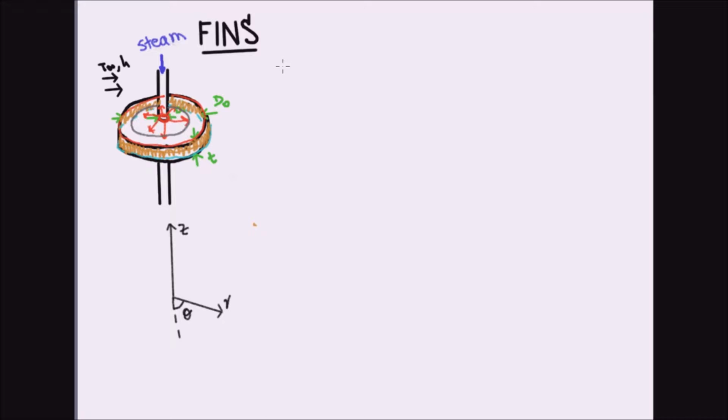This leads us to the next step, which is setting up the differential control volume. So step number 4, differential control volume. The trick to drawing a differential control volume is to set two isotherms really close to each other, so close that the only difference between the two isotherms is just an infinitesimal increase along the direction of temperature dependence. So imagine this is that middle isotherm that I drew, and let's draw another one almost on top of it, really next to it. This one.